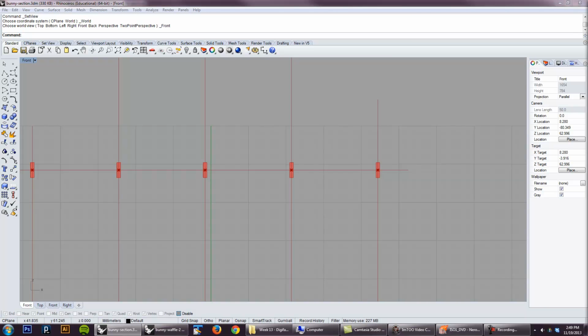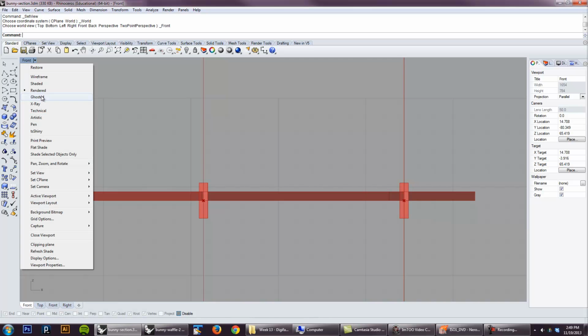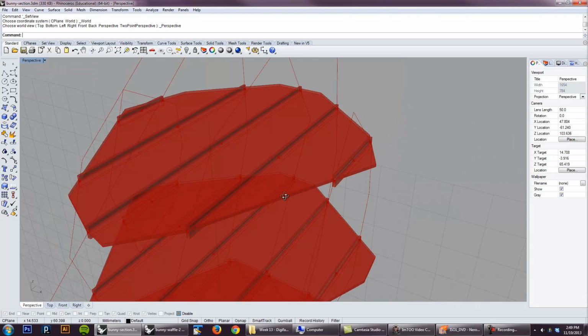And so if we were to take our surfaces and extrude them, and this is just for demonstration, you don't need to do this. This is not quite accurate, but you can see the box that we create just needs to be deep enough to penetrate that, because we're going to use that as a boolean to actually create the finger.